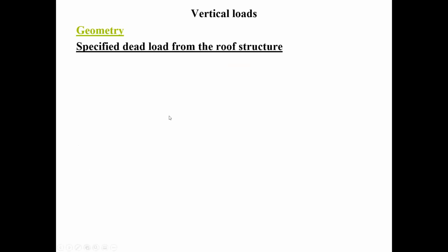Now, specify dead load from the roof truss. So in other words, what we're actually doing is, okay, we have our truss here, and we have our exterior walls. Here's our exterior wall, and of course it's going to be sitting on the floor. So why can I not go and find the forces that are coming into the exterior wall? How do I do that? Well, I've analyzed my truss, so the reactions of my truss will give me the forces that are going into my stud.